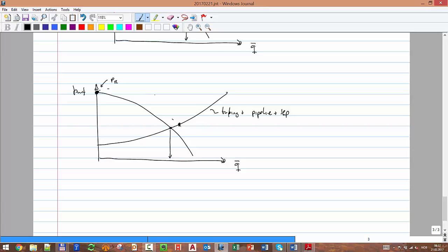Okay, we say no pump. We don't want to change the system, just the way it is. Okay. What happens if I manage to reduce the wellhead pressure or the separator pressure? If I reduce it, I should get more rate, right? So the curve does something like that.